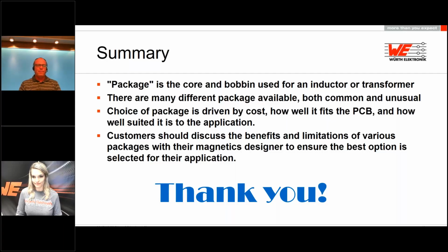So oftentimes with the LLC designs, the customer will want to have the resonant inductor integrated into the transformer. So the leakage inductance that's inherent in the transformer can be used in place of a separate resonant inductor, which is great. Anyone who's designed LLCs knows that that's one way they can take a major component off their PC board, saving cost and whatnot. So what typically happens there is you're trying to increase the leakage inductance over what you would get normally.